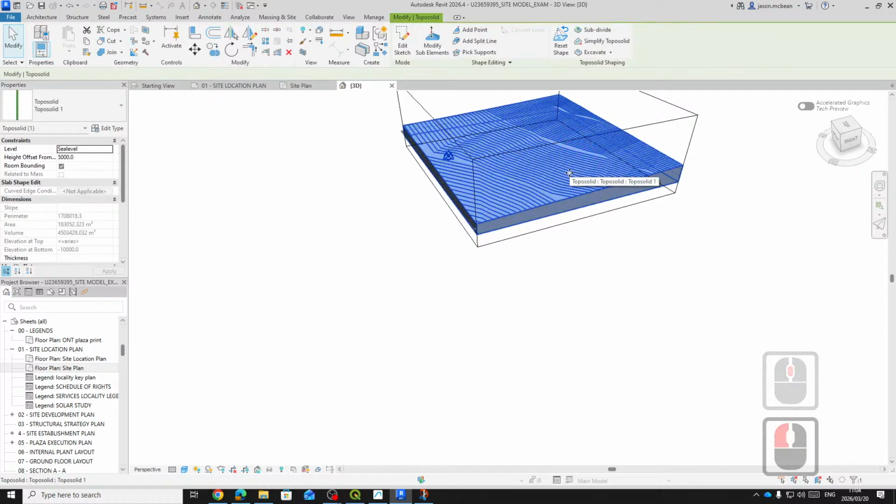Remember, the problem with sites is you want to separate your site model from your building model, because sometimes if you're doing a site intervention, there's a whole bunch of levels that shouldn't pollute your building model. It's actually a separate project. Okay, you want to keep these things separate. You will link them both ways, because this might inform that and that might inform this, but there can also be 2D drawing work that you're pulling in from an external source.